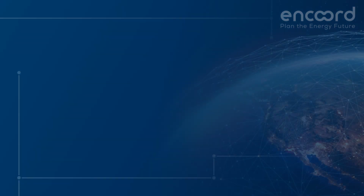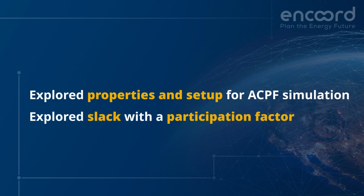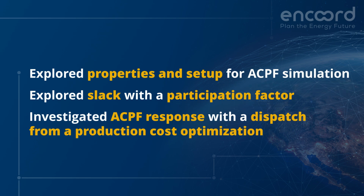In this video, we explored the necessary properties and setup of AC power flow simulations, explored how slack is distributed with a participation factor, and investigated the AC power flow response of a system with a dispatch determined from a production cost optimization, which is a valuable generation transmission workflow.